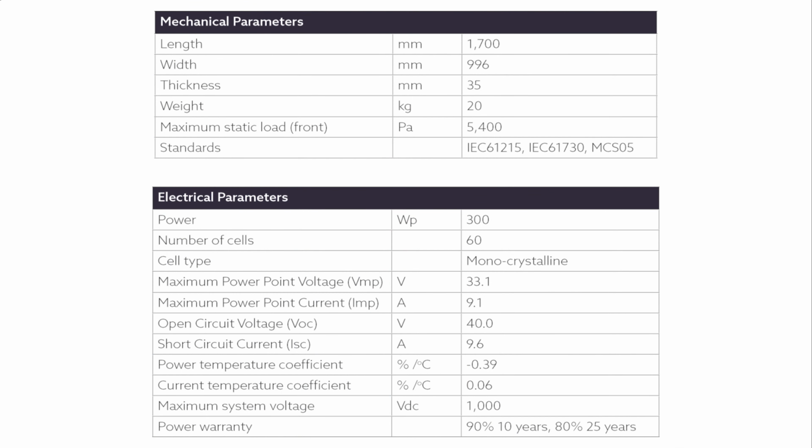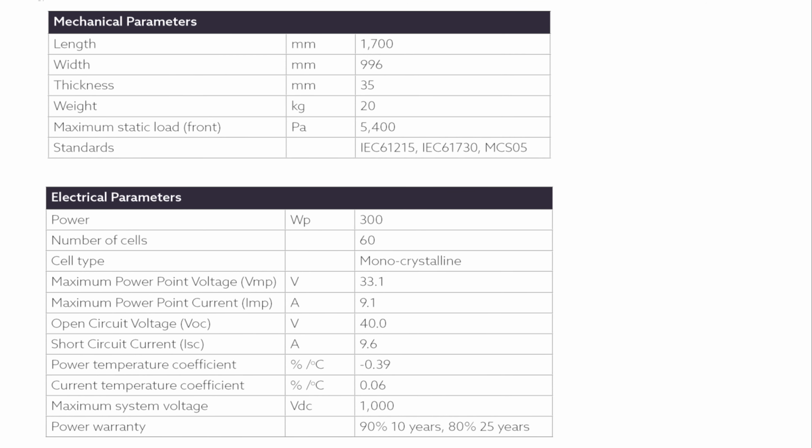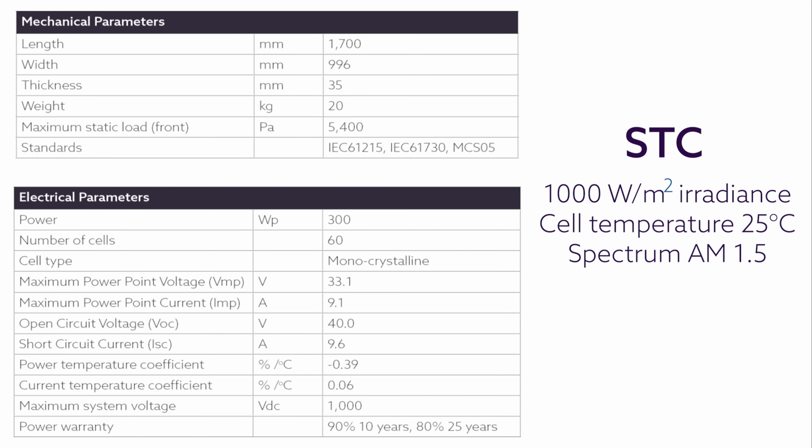Solar modules are sold according to their electrical power, which is measured in watts peak, or Wp. This tells us how much electrical power will be generated when the module is exposed to sunlight at standard test conditions. For a whole solar array with lots of modules, the capacity of the system would be measured in kilowatts peak, or kWp. It's only natural to want to know how efficient a technology is, and the efficiency of solar PV has been slowly but steadily increasing for many years.